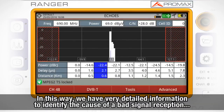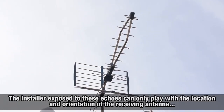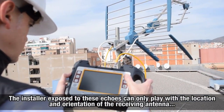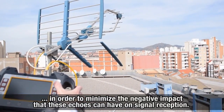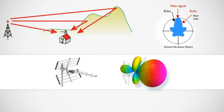In this way, we have very detailed information to identify the cause of a bad signal reception, when other measurements such as power level, carrier to noise, etc. seem to be okay. The installer exposed to these echoes can only play with the location and orientation of the receiving antenna in order to minimize the negative impact that these echoes can have on signal reception.